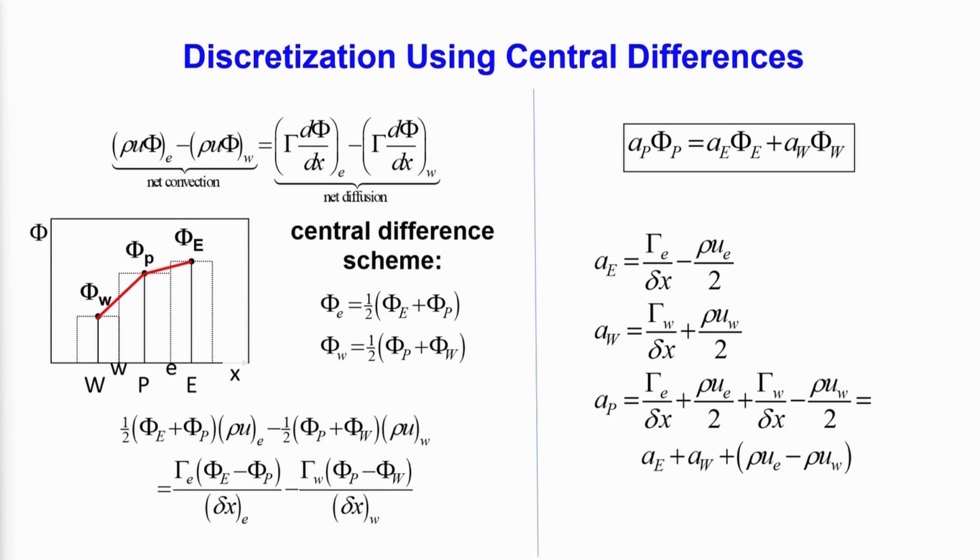That is what we have written, because in your left hand side expression small e and small w values are coming, but the variables which you are solving are based on the main grid points, that is capital P, capital E, capital W, etc. So, that requires interpolation, and here whatever profile we have used for the diffusion term, the same we are using for this so called convection term and putting in that interpolated value.